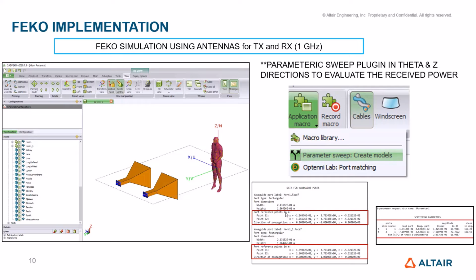You can see these are the out files, which are going to have the position information as well as the transmitted and received power from the horn antennas. S11 means the scattering matrix reflection coefficient, and S21 is nothing but the transmitted power, the transmission coefficient, of this particular simulation, of this particular configuration, whatever we have in this simulation.